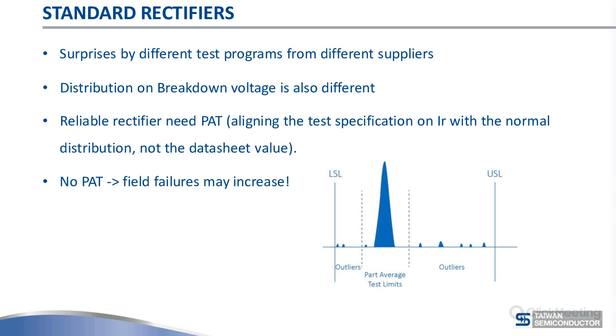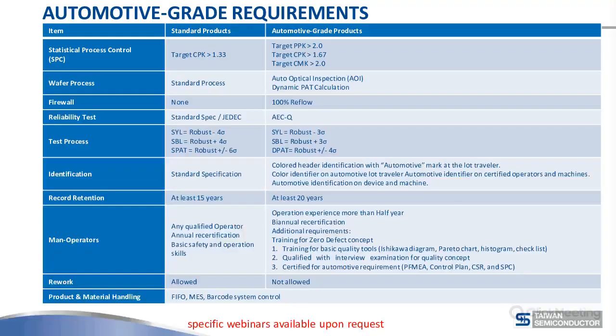Your field failures will increase depending on your temperature and how much you challenge the device. Your field failures may increase if you switch source. So this is one of the more hidden issues when changing rectifiers or cross-sourcing rectifiers. The next slide is made by my colleagues that work in quality, and it tells you a little bit of the difference between automotive and non-automotive parts.